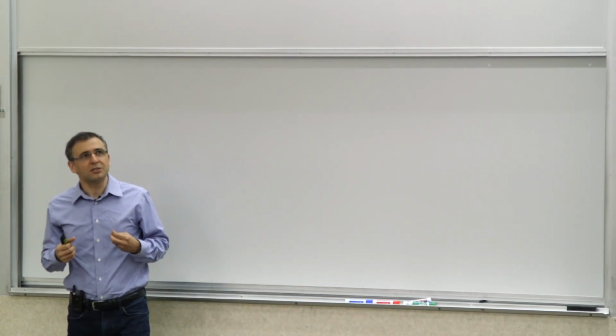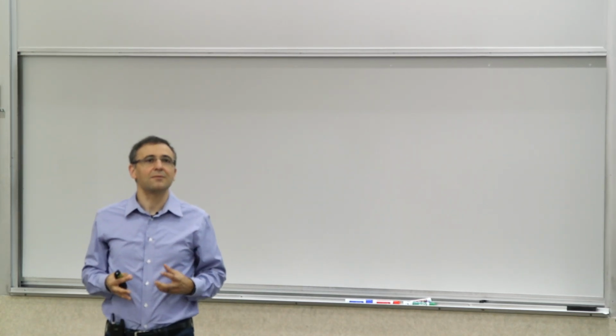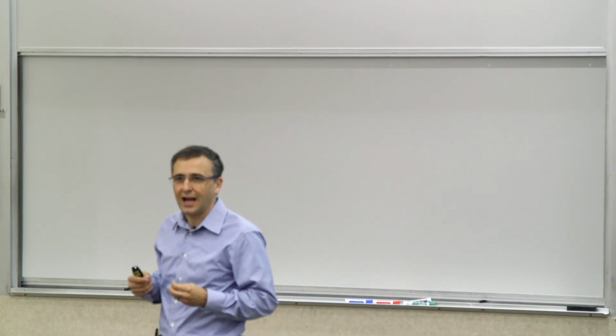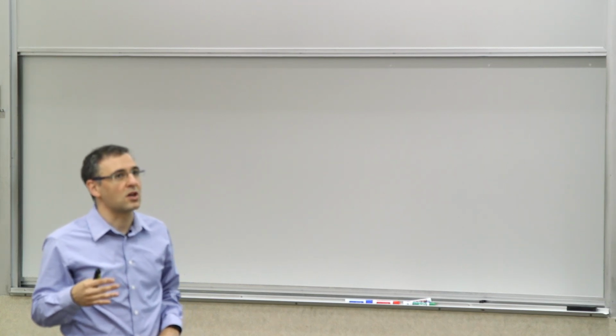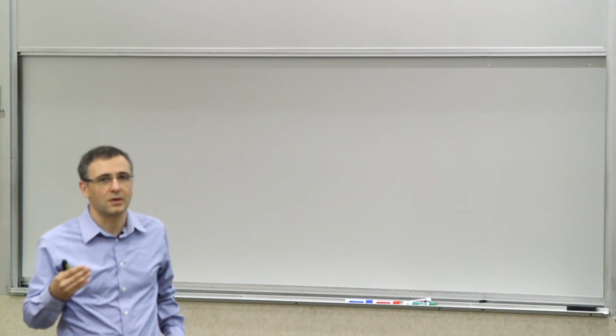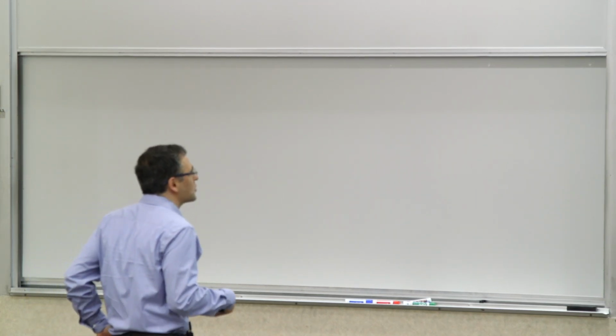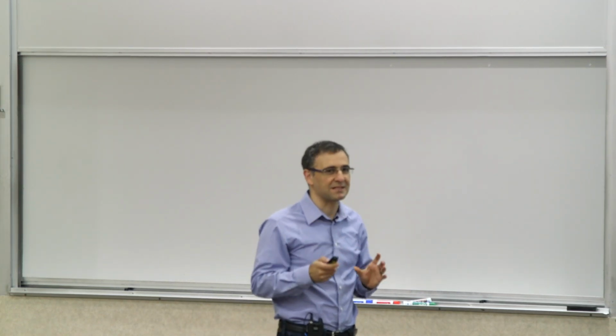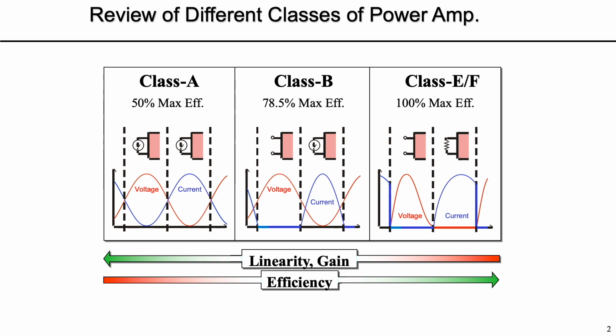So the key question is: how do we do this? The focus today will be mostly on RF power amplifiers, and it's an introduction to that, with a fair amount of focus on switching power amplifiers, although we are going to be talking about non-switching linear ones along the way. Before we start talking about specific topologies, there are certain rules and relationships that matter in power amplifiers. If you think about a power amplifier, they really form a spectrum.